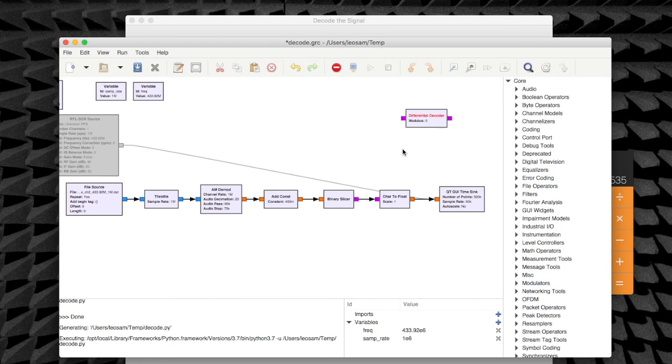Finally, you need a frame decoder in order to extract the information inside of the frame. We already know that the 4 first bits after the differential decoder will be the channel. The 4 next bits will be the device.